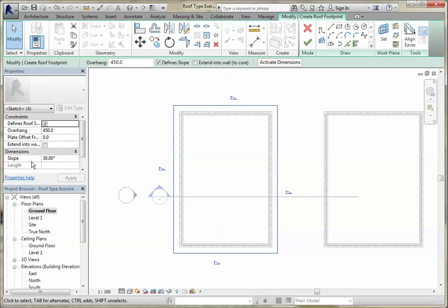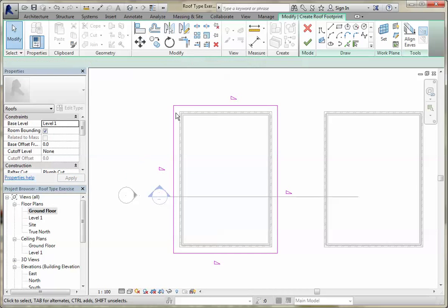And you see in here you can adjust the slope of the roof. So I'm going to make this one 25. You can make it whatever you like when you do your exercise, but just realize that you might want to play around with it later and do another change on it to see what it looks like when you change the angle. So I'm going to make this one 25 and bring it over. As soon as I come onto here, that change has been made.